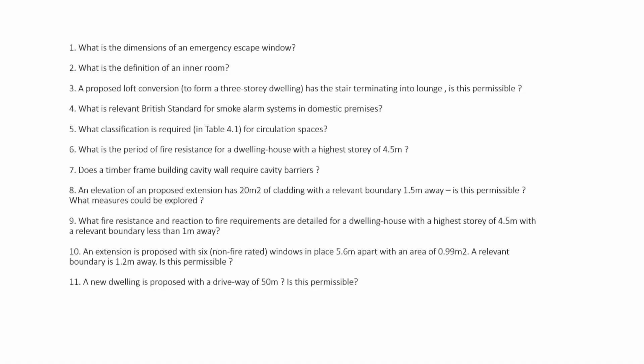Happy? Should we have a quick stab at running through them? Hopefully it's kept you awake a little bit after lunch. So, dimensions of an emergency escape window. Anyone? Yes? 450, 0.33, 1100. Definition of an inner room.